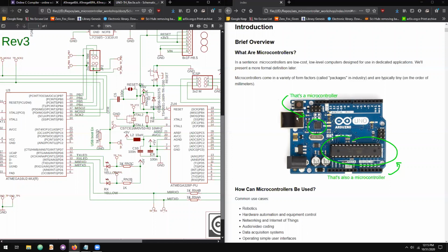And I wouldn't recommend using a bootloader method until you have your application code fully debugged. So in practice, it would look like you would get your new board in, you would connect your programmer debugger, load code that way using that method, and do your debugging. So via, in this case, the debug wire interface.